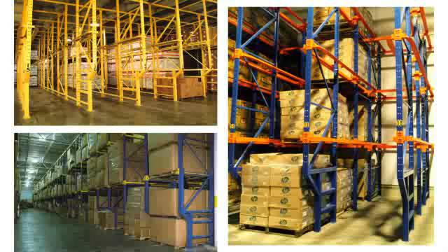You notice that this rack consists of upright frames. On the top are horizontal stabilizing beams. Then you have basically what they call the arms on the foremost frames, and on the back there could be horizontal or tie beams in the back frame there. And then there's this load rail that runs parallel with the upright frames in the direction of travel, and that is actually what the product is set upon.